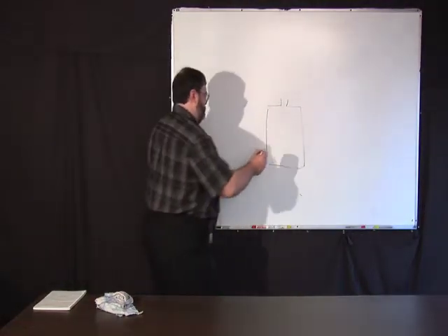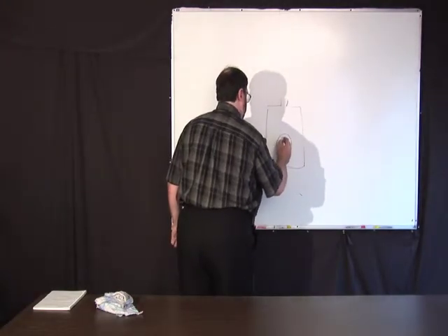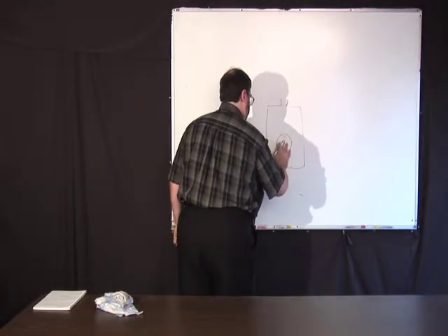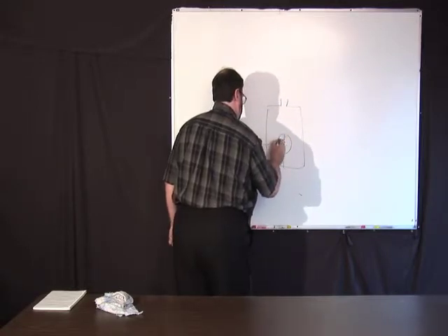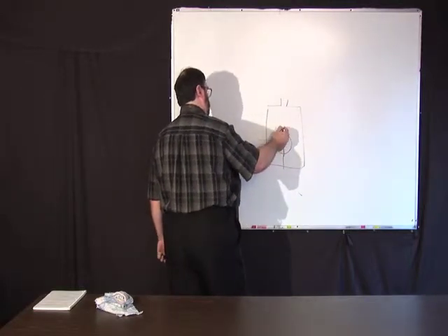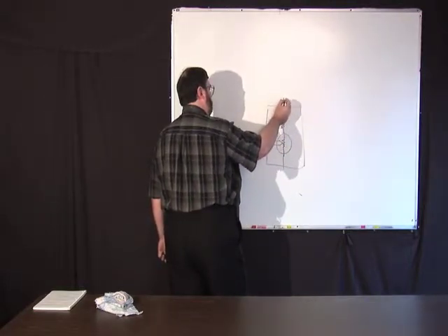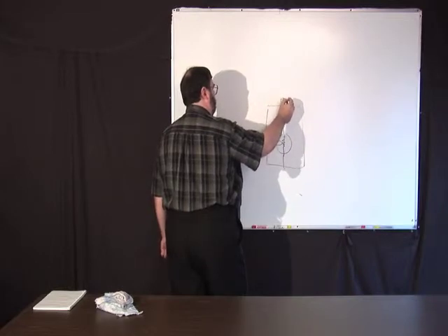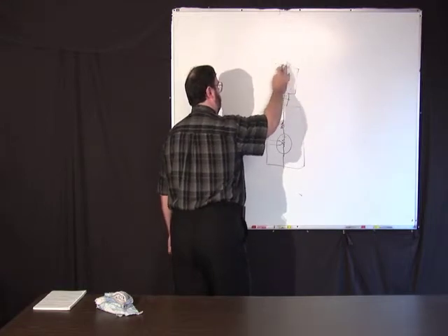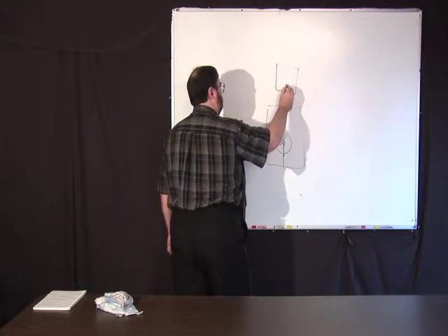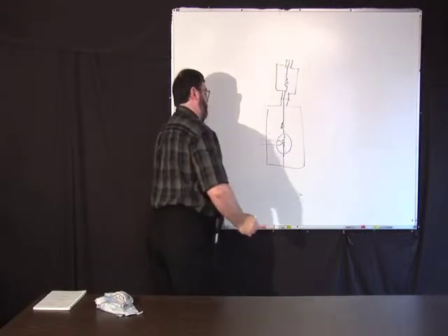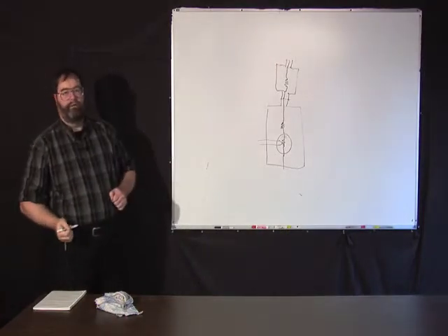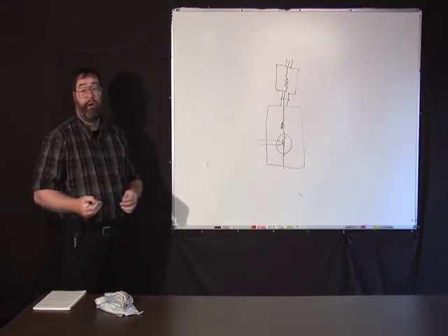You put your thermal element in there, and your thermocouple output. There might be another resistor in here. And then what they sometimes do is they make what are called range resistors that you attach to this thing, which has some other precision resistor in there to change the voltage dividing so that you can cover a wider range of AC or RF voltages.